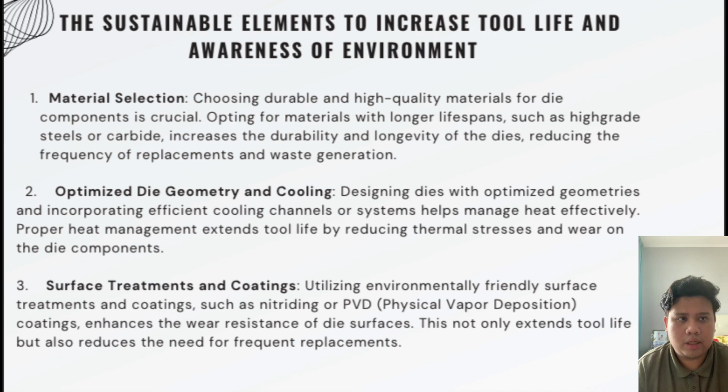Optimize die geometry and cooling. Designing dies with optimized geometry and incorporating efficient cooling channels or systems helps manage heat effectively. Proper heat management extends tool life by reducing thermal stress and wear on the die components.